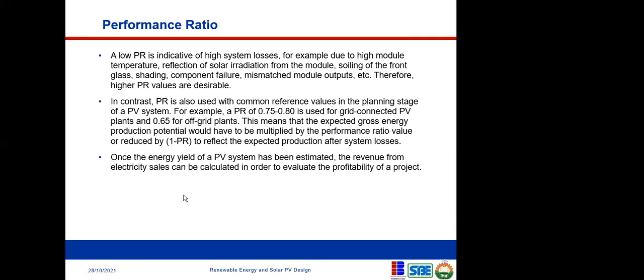Did you get me, sir? Yes, I got you. I heard what you said. You're correct. Like that work I told you about, where we had a complaint because of the tank, what we did was add 4 more panels before the system became stable. Yes, that's what I'm saying. The lower your performance ratio, the more panels you have to add to get the energy output that you want.